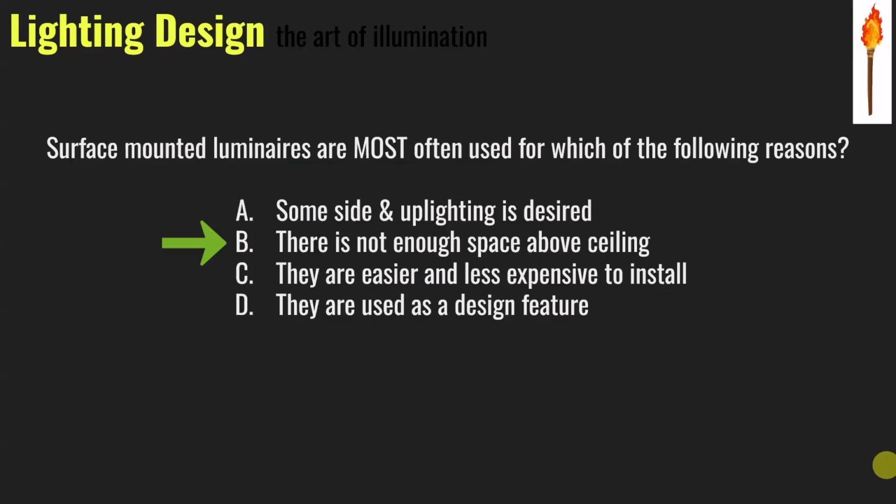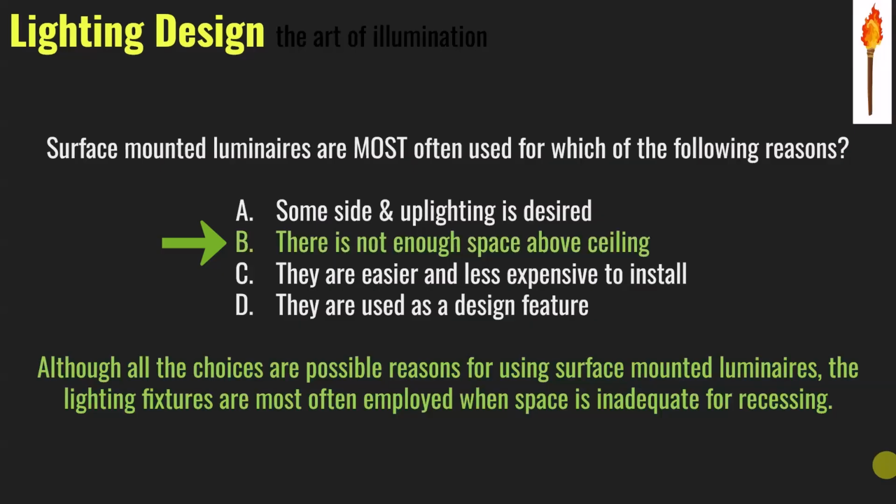Precisely. That's exactly where they're most used. What makes that an important type of fixture to have? Okay, not enough space above. There's no plenum. We have solid slab ceilings, and then not particularly high ceilings, although this is definitely, I think, better than what's in the other spaces. That is a solution, is the surface mounted, right? That's almost the only time they're used, is when there's not enough plenum space.